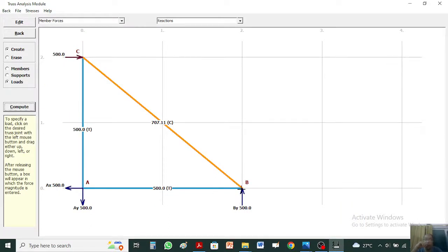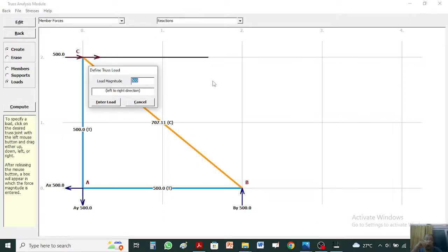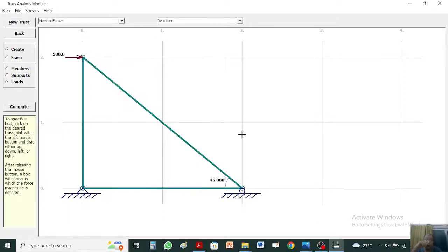Okay. Now this vertical force is compressive, and if you look at it, AX and AY are tensile forces. This is a tensile force, this is a tensile force. Remember this thing along point A. And if you want to further elaborate the directions, you can ask for the directions at these 3 points. So this is a simple calculation. I will make another video on doing tougher computations of trusses. Okay, it will help you in your future assignments.